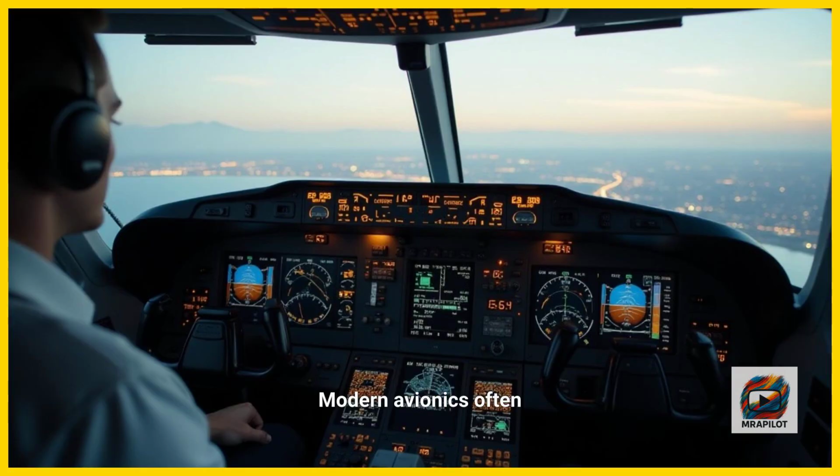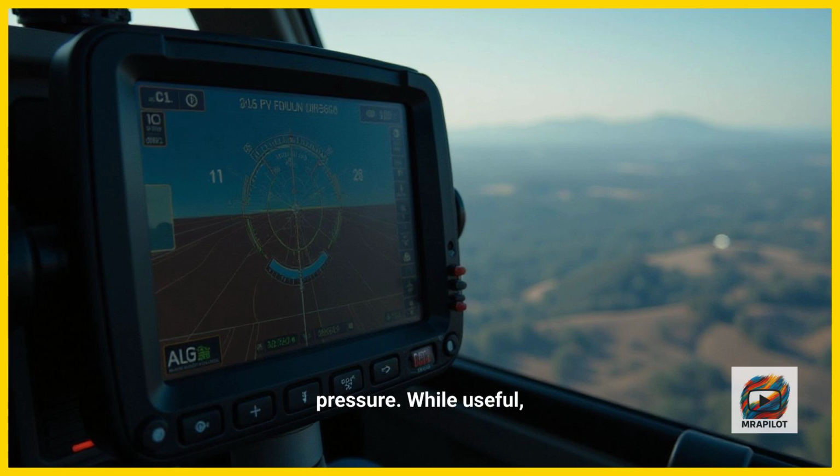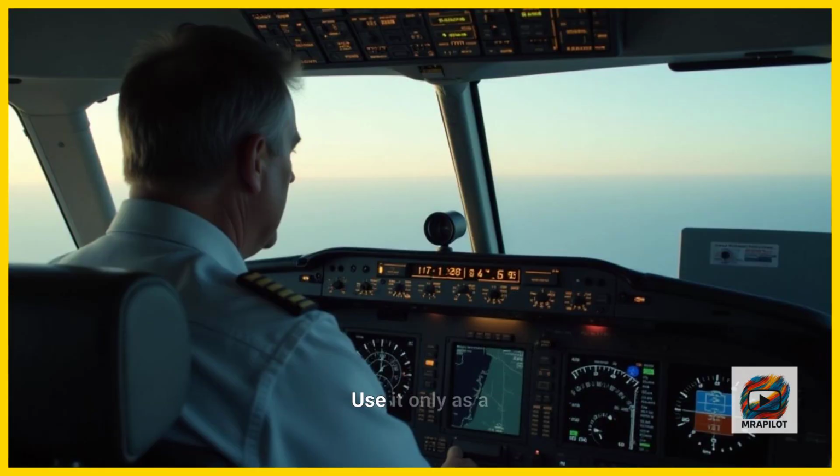Modern avionics often display GPS altitude, which is based on a geodetic model of the Earth, not pressure. While useful, GPS altitude isn't used for separation. It doesn't reflect terrain clearance or standardized pressure levels. Use it only as a backup.